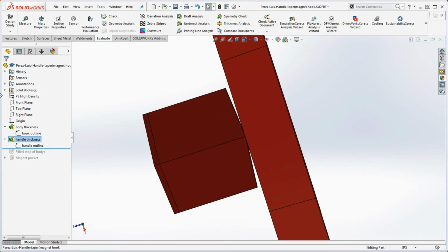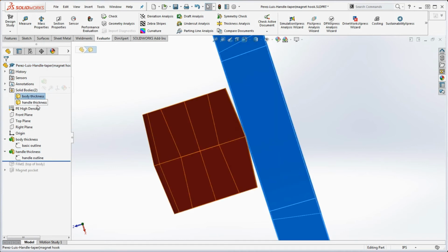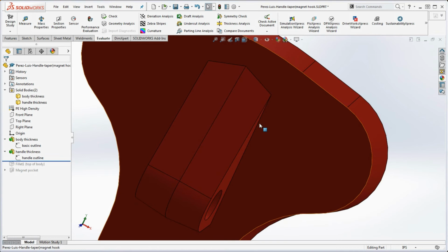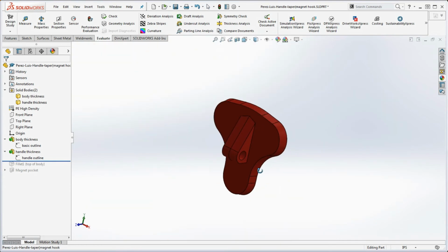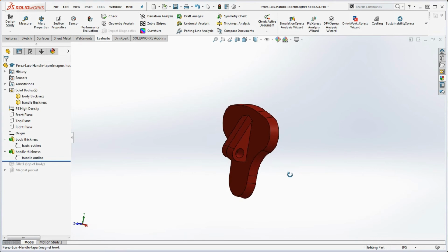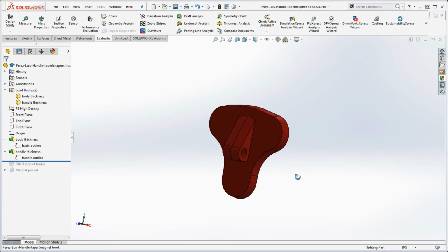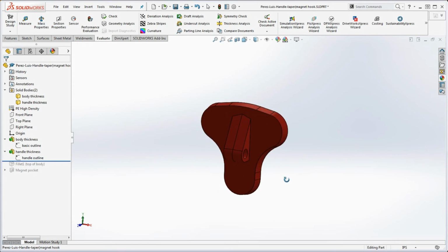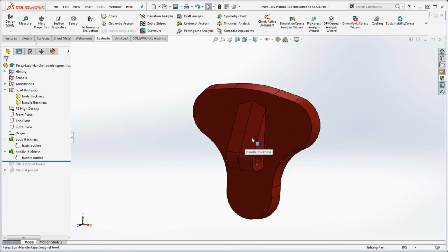So what you end up getting up here are 2 solid bodies. You have the guy in the back, you have the guy in the front, and you're never going to be able to put a fillet around that. Now, conceivably, you can take some of the sketch geometry in the back and do an extrusion to the next surface and other things. But this is the reason why we do this draft as a separate feature in situations like this, because you get geometry that you just can't work with unless you do some additional work on it.